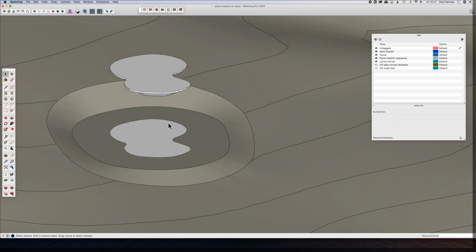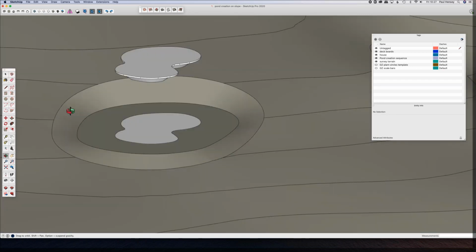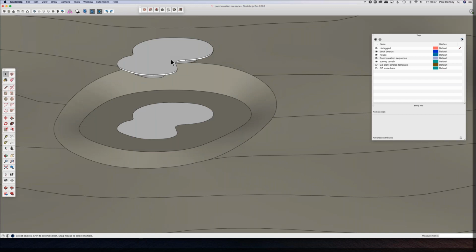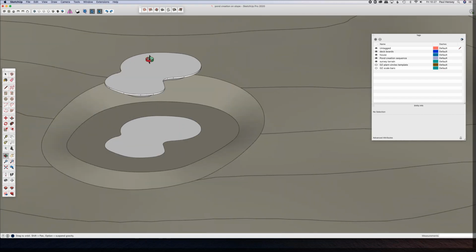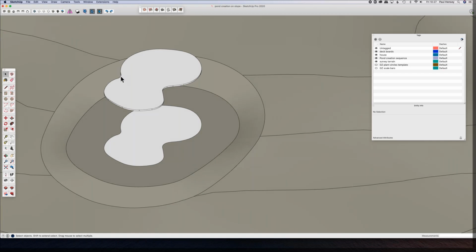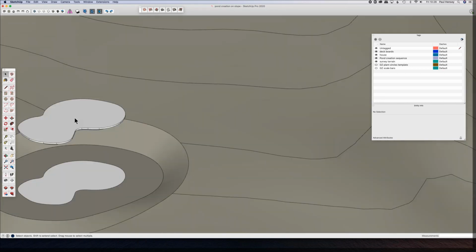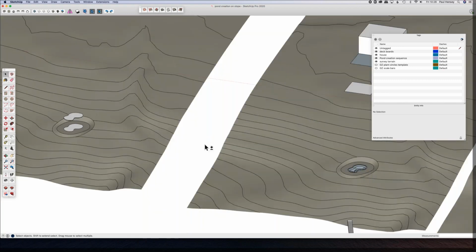So that is a neat way of getting a cut and fill, because now I can tell somebody that in order to excavate this, you're going to be removing 21 to 22 cubic meters of material. The other thing it's quite useful for is on things like ponds and features, you can then work out the volume, which will then help determine the value of things like pumps and filters and power requirements and how frequently you want to turn over the water.